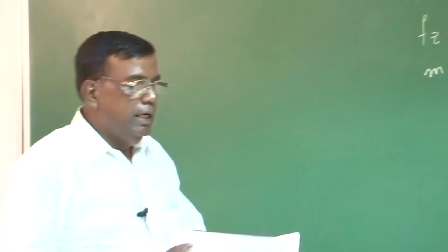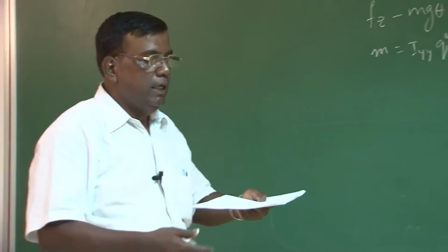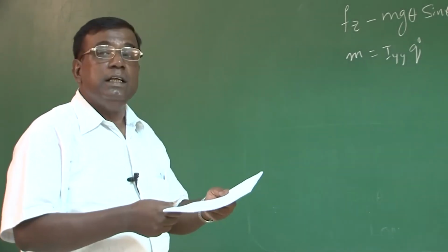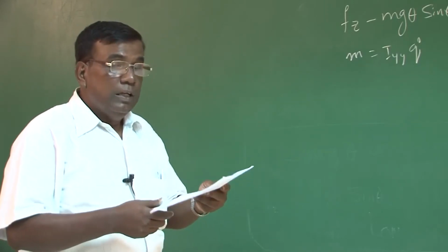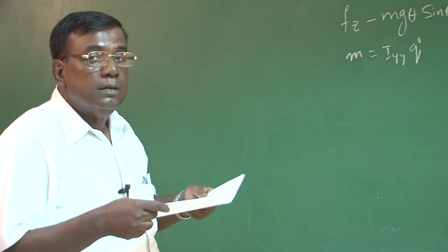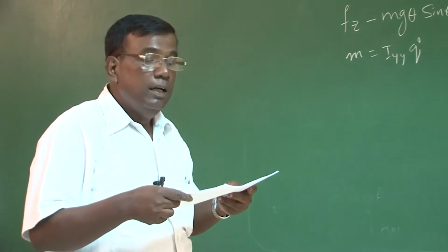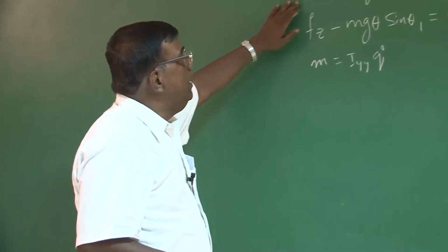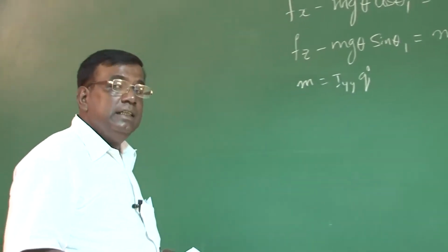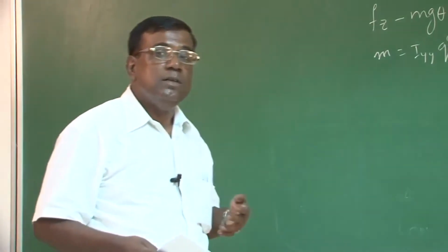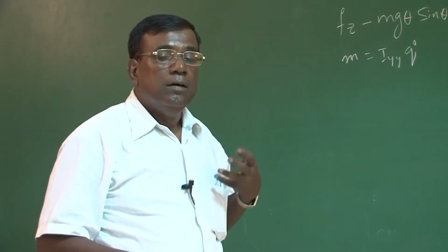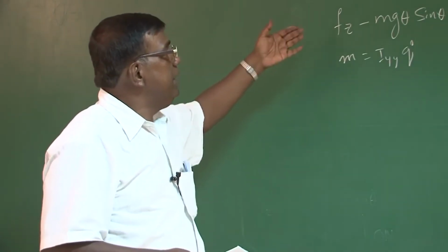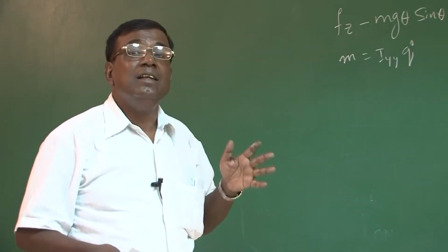Because you understand, if the airplane is at steady state like this, and if there is a disturbance, then this angle of attack will change, pitch rate will change, right? So the perturbed aerodynamic forces, which come because of lift and drag, also will change. So I need to explicitly know how this Fx, Fz, and m are changing. To know that, first I must know mathematically what are those motion variables, what are those control variables on which Fx, Fz and m largely depend.